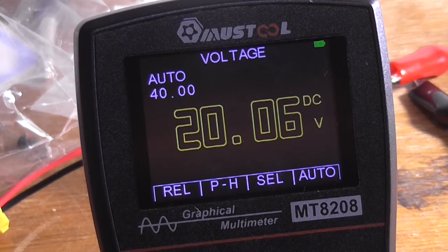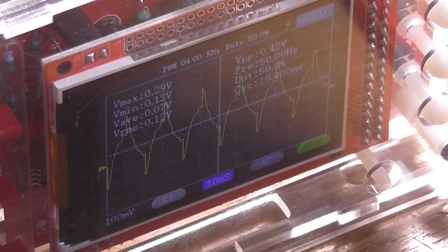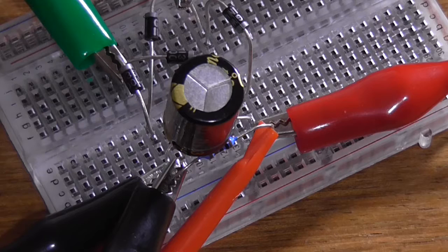See that? Now it is at 20 volt DC. Why? Because now with the filtration capacitor in there, we're using the square root of 2, which is 1.414, multiplied by the voltage coming out, which is 15. So it equals roughly 21 when all said and done. And if we look at the scope, the ripple is reduced, but it is kind of nasty looking still. So 470 microfarad is not going to fit the bill. So what do? Well, we increase the capacitance.